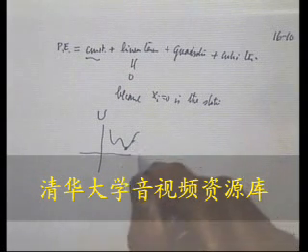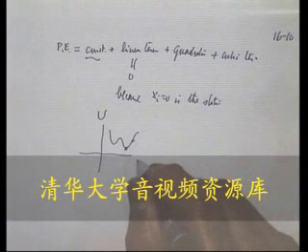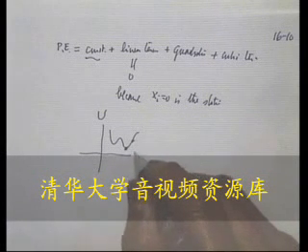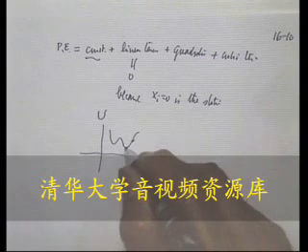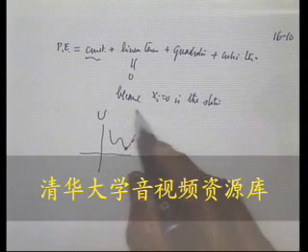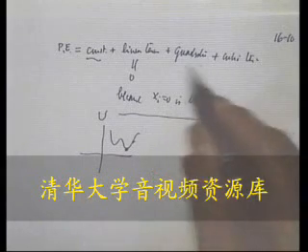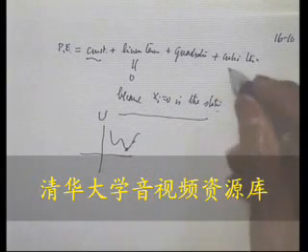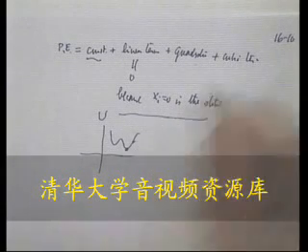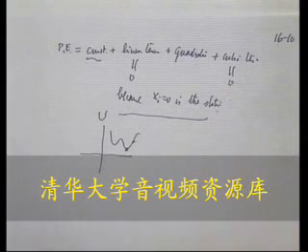If it's at this point, there's a linear term, but that's not a point of equilibrium. At the point of equilibrium, the linear term always vanishes. So that's why this is 0. So therefore, we only have a quadratic term. And these cubic terms for small vibrations are very small, so we also drop them.